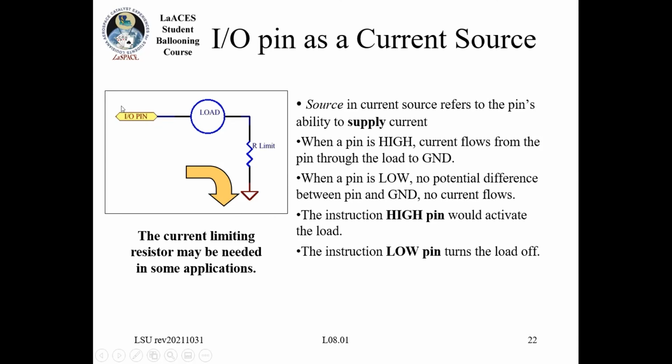But this IO pin is not like a power supply. It's a little bitty IO pin going through some small traces. It's not meant to supply power. It's meant to supply a digital signal.